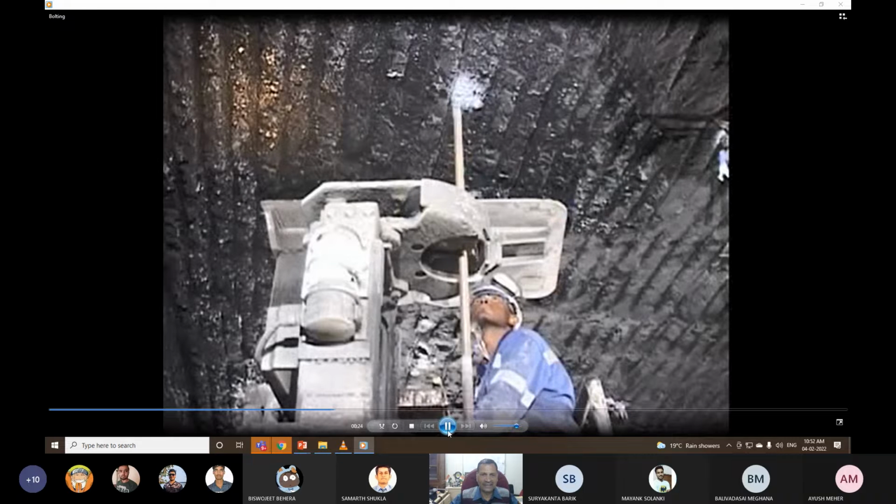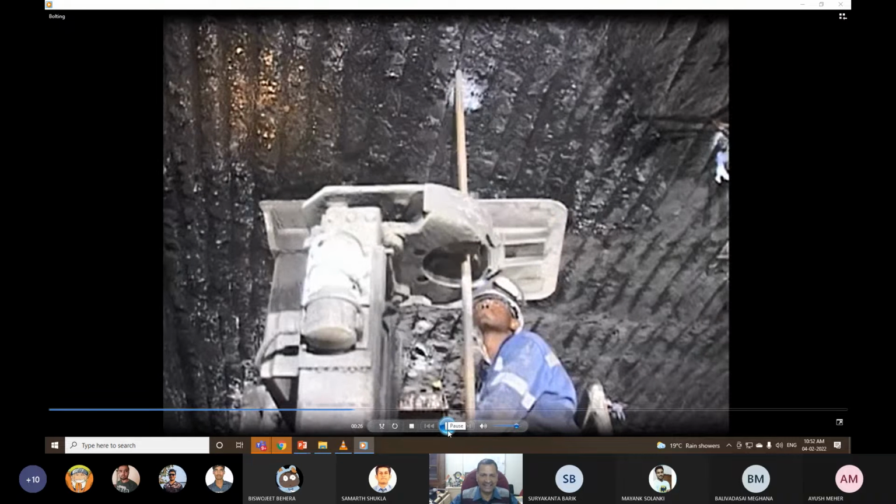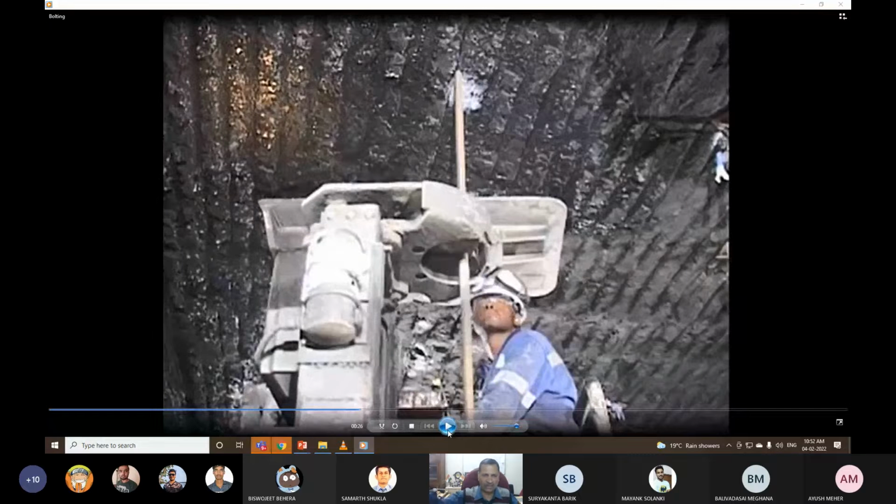And here, drilling is done in that cycle of supporting. First, we drill the hole, then clean that hole, then insert the rod, and then your cement or resin, then allow it to settle, and then if it is a pretension bolt, give that pretension. Otherwise, you can provide a nut and assembly so that you are installing the total system. Now you can see how it is done.